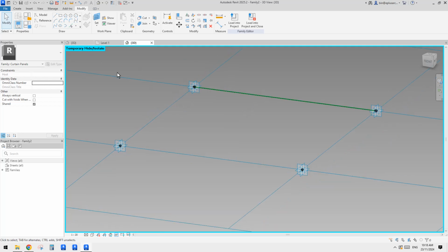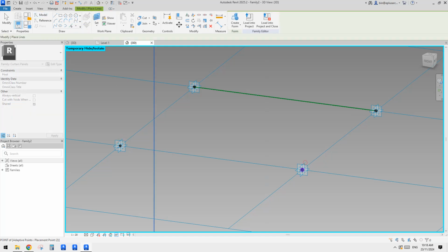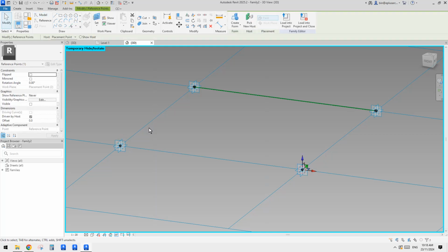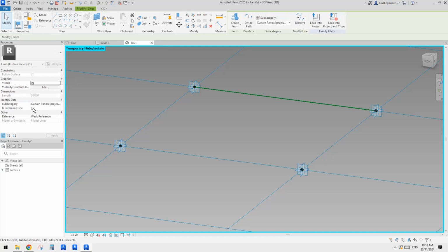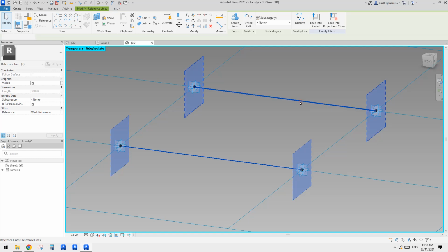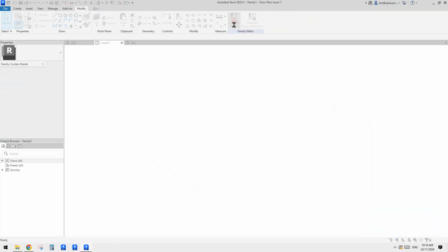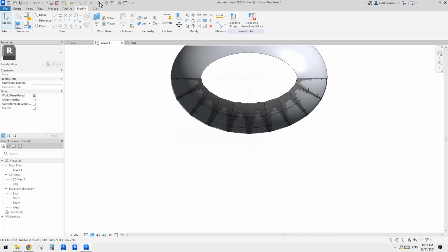And if I do another one on this side, and the same, select the point, so -10, and this one 10, and select all 4, create spline through points, reference line. So now if I use these 2 and create a form, and then load this one in here, let's have a test. Let's go to 3D view.